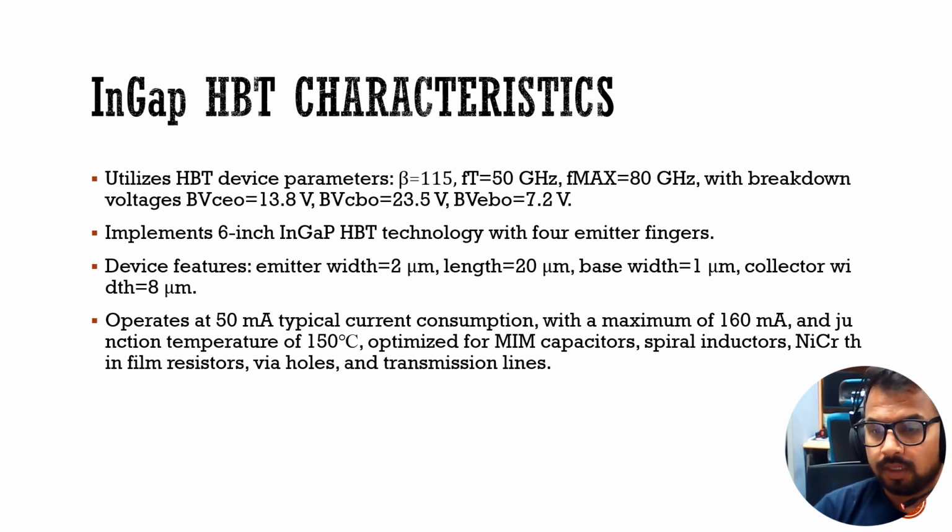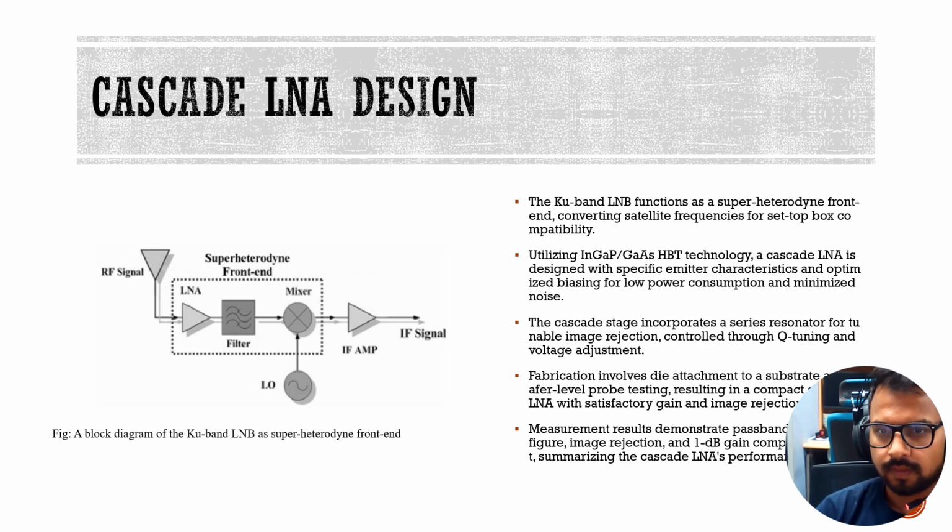It operates at 50 milliampere typical current consumption with a maximum of 60 milliampere and a junction temperature of 150 degrees Celsius, optimized for MMIC capacitor, spiral inductor, NiCr thin film resistor, via holes and transmission lines.